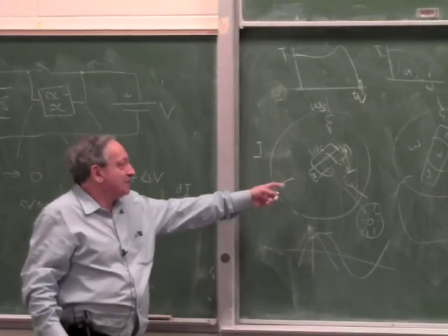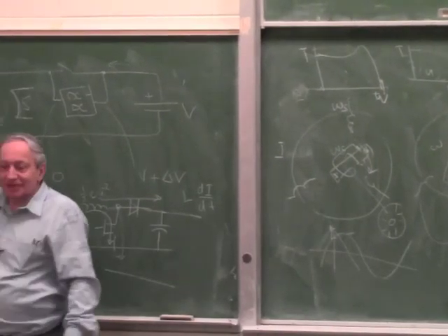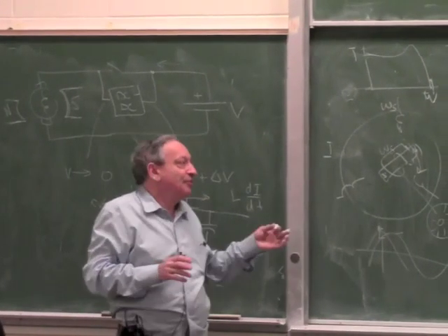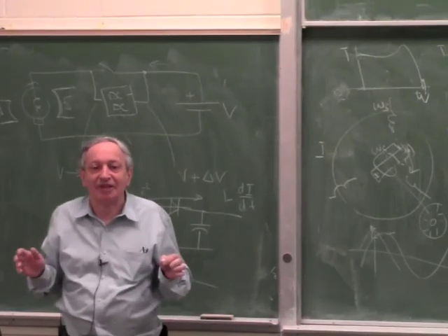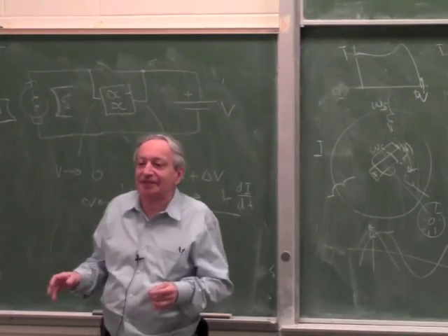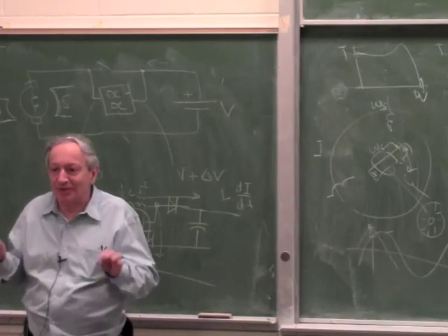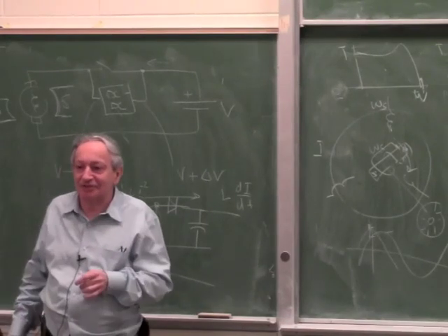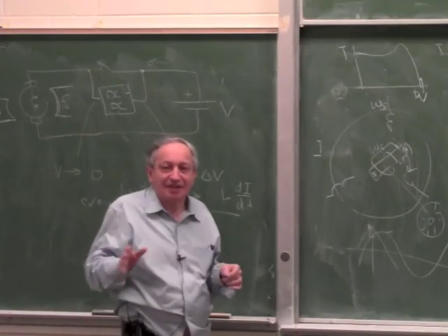Because this one, the induction motor, doesn't have a magnet, and this one doesn't have a magnet, but it still can feed power back to the grid. This is only important in big systems, or systems which have to be super efficient, like an electric bike. But in a normal servo, unless it's a multi-horsepower servo system, you don't bother with it. Because if you want to brake, you just dump the energy into a resistor. The only exception I can think of is electric bikes.